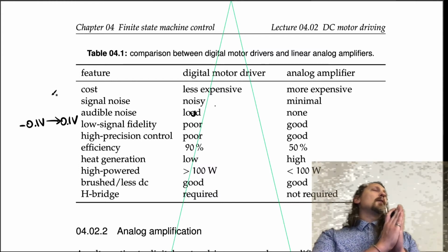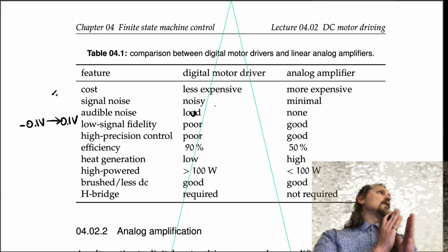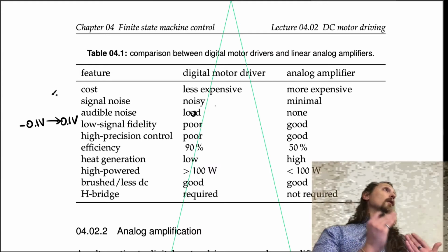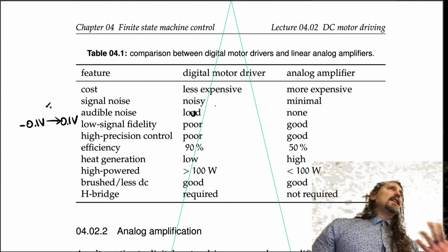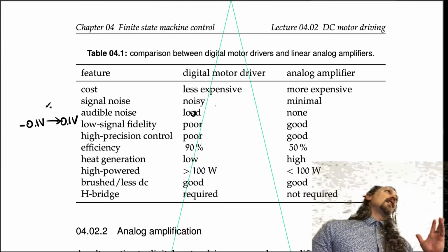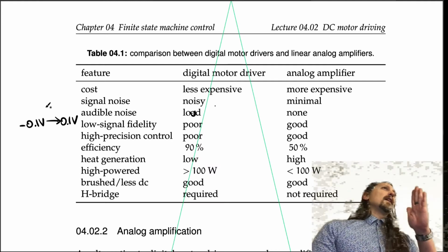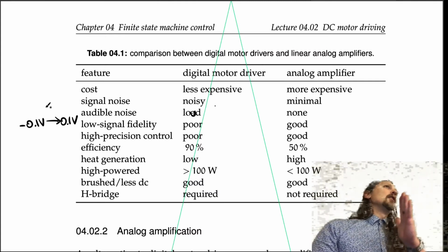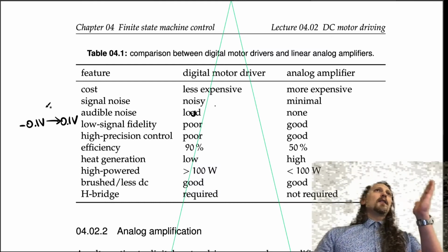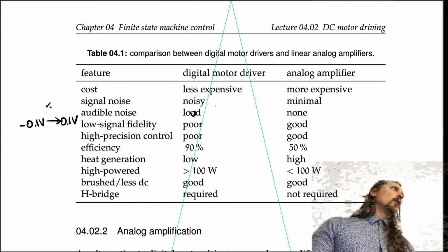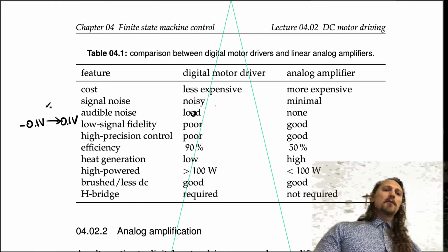The higher frequency you're working, the better, but it's tough to get really good resolution when you get down near 0 volts, at very low duty cycle. If you have this issue, you'll have a really hard time stopping at a precise small value of anything. It'll kind of float back and forth, and that can cause your motor to move back and forth potentially, or there can be other issues that arise with the low signal fidelity.